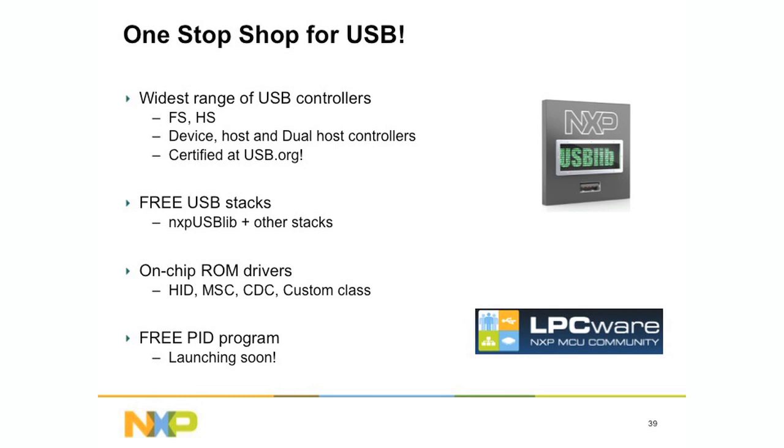So if you enumerate, our evaluation board has a mass storage class, it will show up on the PC as a drive. So your 32K of flash maps to the PC as a drive. And to update the firmware, you just do a simple drag and drop, and that's pretty much it.